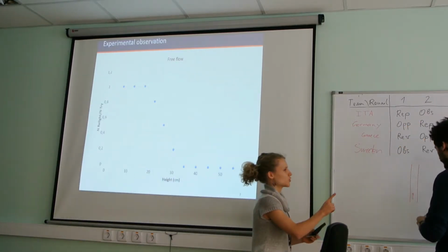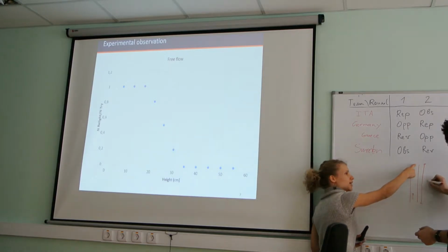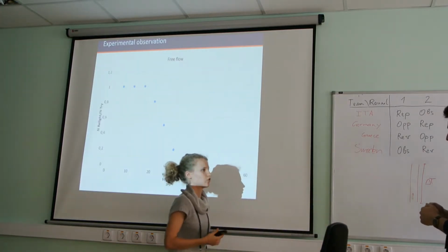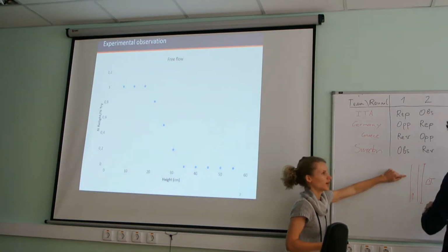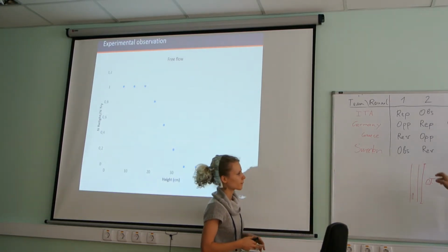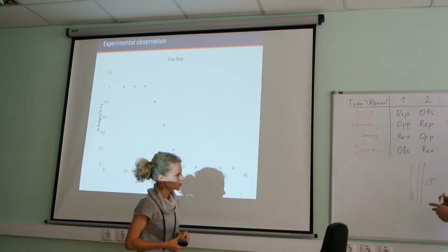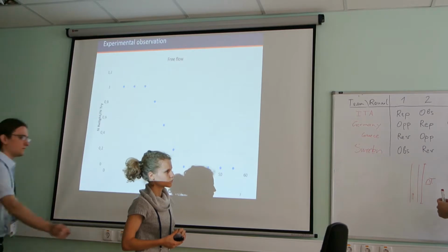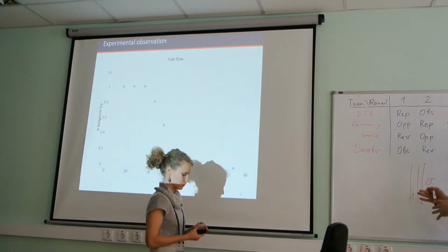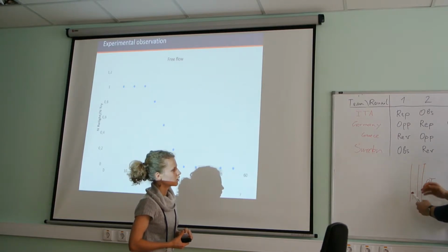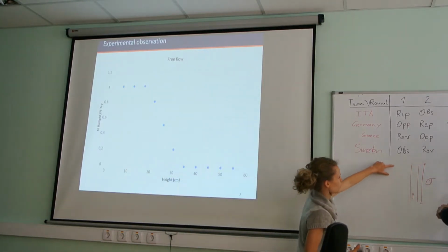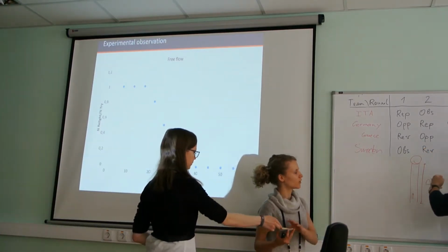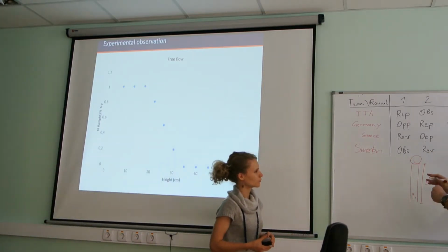Okay, but just to get it clear, is the point here where you can still see the laminar flow, or is this really the point where it changes from laminar to turbulent flow? Is it here, or further down or up? In this motion it's a bit strange, because in the tube the flow is still quite laminar, but it's in the transition state. It's not perfectly laminar. But you don't have diffusion in this direction. Yes, but where exactly do you have the change between laminar and turbulent flow? The change is over here, because the smoke starts to perturbate. Here we have a steady, stable flow.